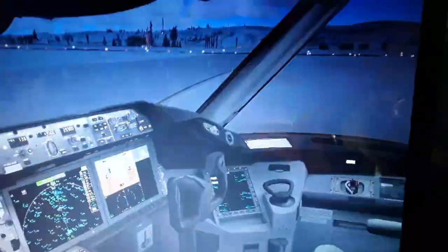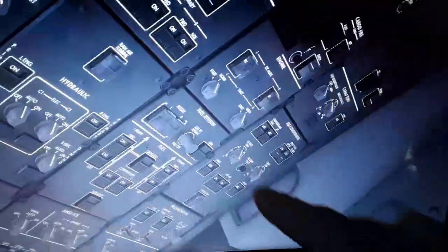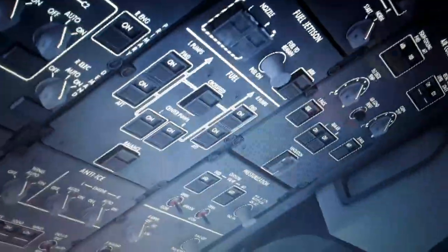Also from the engine we receive oxygen regulation over here in the flight, cabin pressurization. You see also the hydraulic fluid tanks pressurization. All these are controlled by the FADEC. The FADECs are the full authority electronic control computers, one installed per engine gearbox, as redundancy. When one fails, the other takes over, controls, monitors, and displays all the engine data. We see the engine indication.